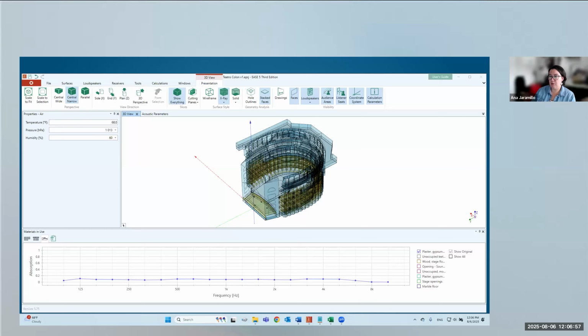So in EASE 5, you can certainly calculate intelligibility and coverage for PA systems, for public address or alarm systems. However, you can't add multiple rooms in the same file as you do with EASE EVAC. You need to do one room at a time. Or you can do multiple rooms as long as they're connected, in a single air, a single envelope.